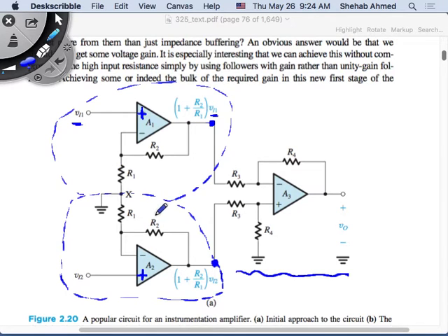But if I properly choose the resistors, then I can sort of eliminate it, right? But that was still the same as my previous circuit. What did I buy myself? What I bought myself here is, in the difference amplifier, for me to have a large gain, I had to compromise input impedance, right? So I want something that buys me some advantage over the previous circuit.